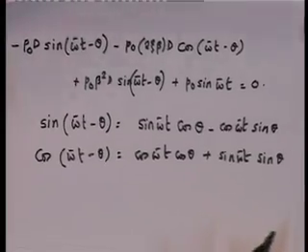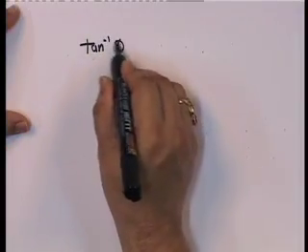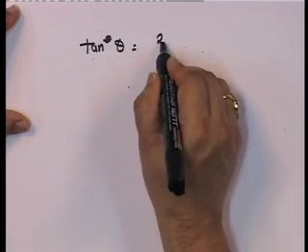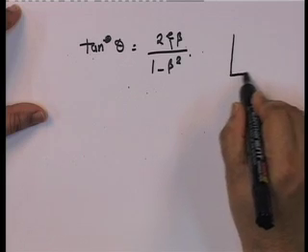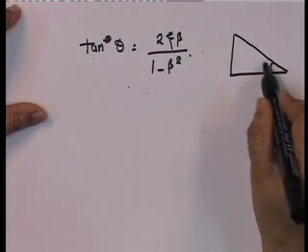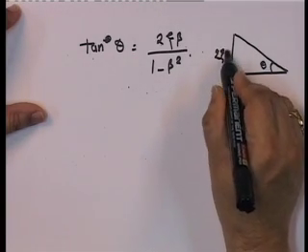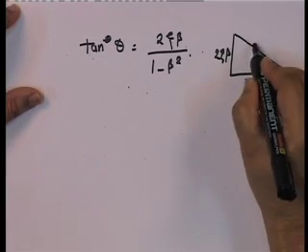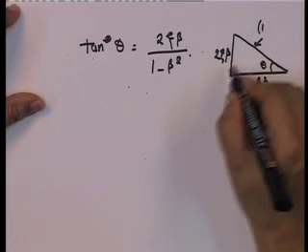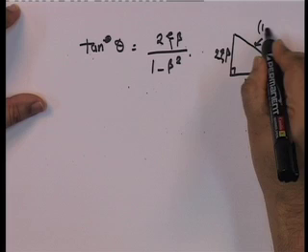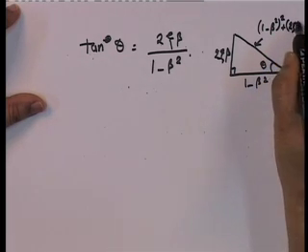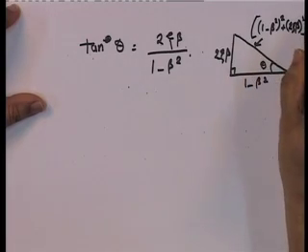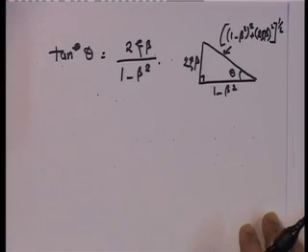Furthermore, we know that tan theta is equal to 2 xi beta upon 1 minus beta squared. So, this, as I drew last time, was this. This implies that if this is theta, this is 2 xi beta and this is 1 minus beta squared. So, obviously, this is equal to, by Pythagoras theorem, because this is 90 degrees, the square root of 1 minus beta squared plus 2 xi beta squared. This is the Pythagoras theorem, right?